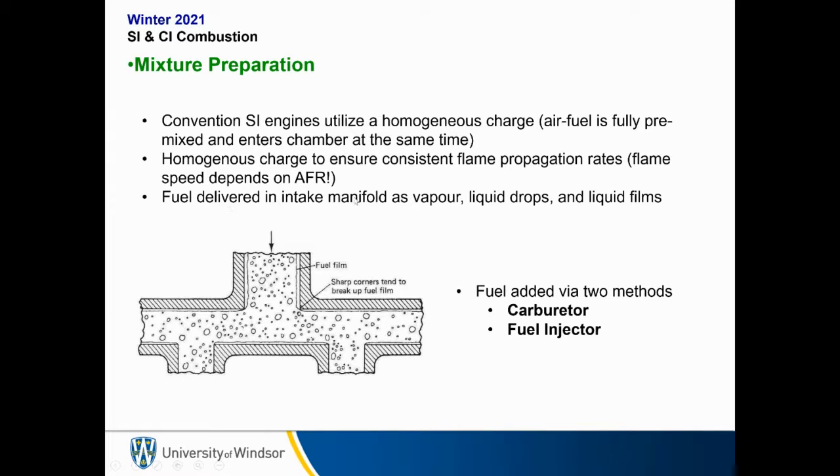So fuel delivery in the intake manifold is vapor, liquid drops, and liquid film. So it's a really complicated process in that we don't have fuel just being delivered as a gas. We have it as a vapor, a liquid drop, and a liquid film. So it's actually quite complicated getting the correct amount of fuel into the engine.